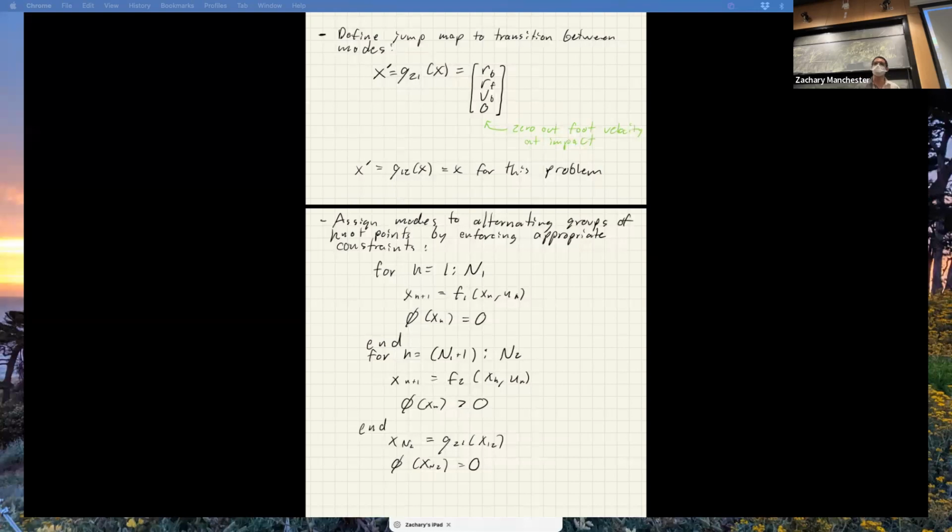That's exactly what I was just going to get at. While this seems very restrictive, in the case of a hopper it's not at all, because I can do the free final time thing where I make the h's for each time step variable. So I can let the solver stretch and shrink the actual times between these mode transitions and generate more interesting things.